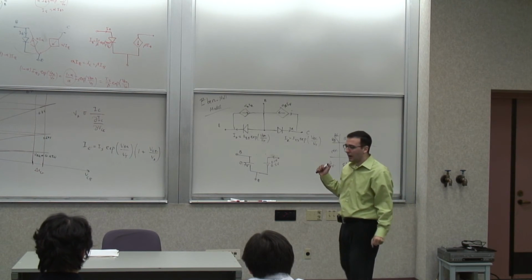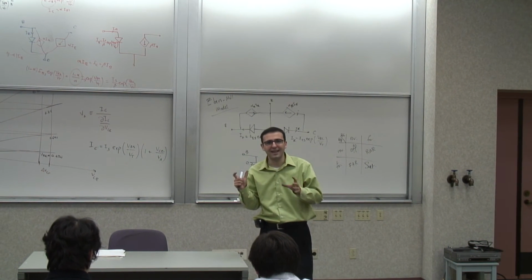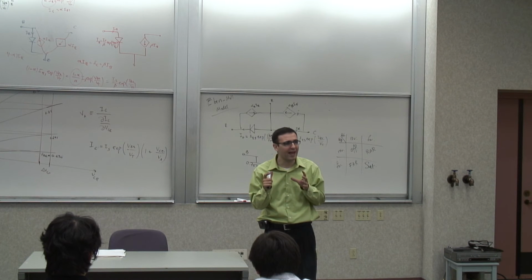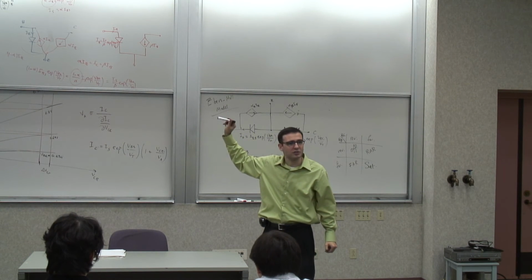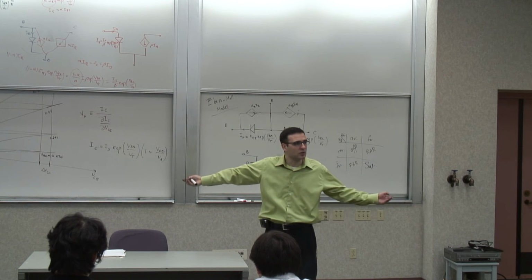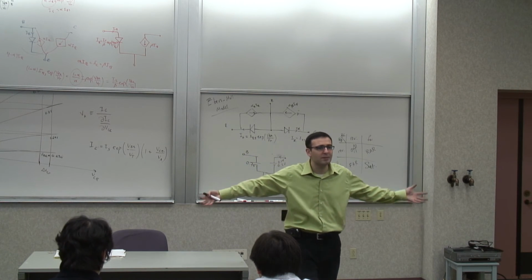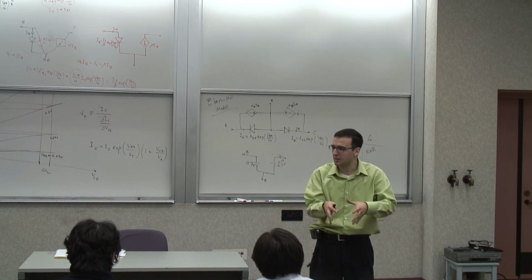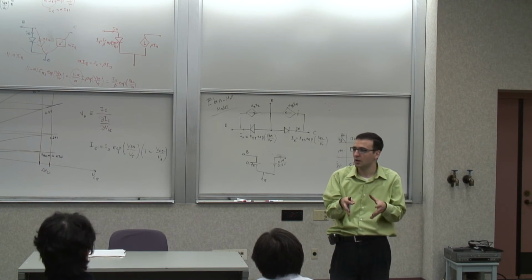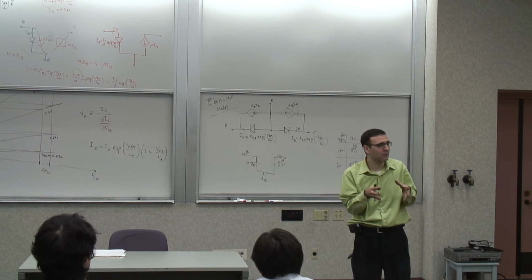Now, from a dynamics perspective, it's also interesting because once the transistor enters this mode, and we'll talk about it a little bit later, you have a huge buildup of minority carrier charge in the base, right? Because both junctions, both the collector and the emitter, are dumping electrons into the base, in the case of an NPN, or holes in the case of a PNP. Minority carrier charge.